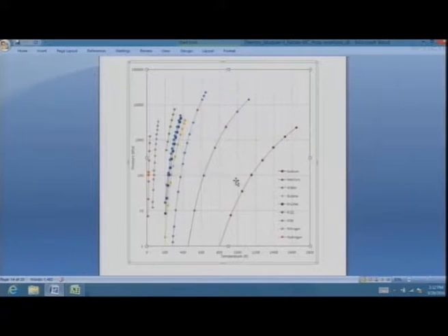And so this refrigerant R12 I have not put here, but R22 is a little bit still in use, but it is slated to be banned, and we are moving out to R134 and other refrigerants where chlorine is much less or if not there at all. So there was a huge environmental problem with these materials, and while they were very popular for a very long time, starting about 20 years back, the global community decided that we don't want this, they are too bad for the environment, we should go for more eco-friendly refrigerants. That's what you see happening today in ACs and refrigerators.